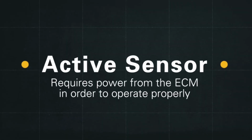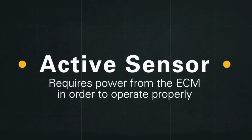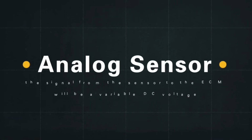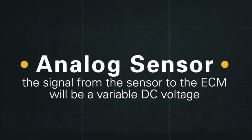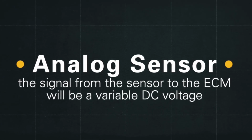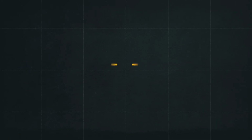We said we're going to be troubleshooting a -3 FMI code on an active analog sensor. Before we get too deep into the troubleshooting, I want to make sure we understand what we mean when we say active analog sensor. An active sensor requires power from the ECM in order to operate properly. In this case, we're dealing with a 5-volt sensor. Analog sensor, what does analog mean? Analog means that the signal from the sensor to the ECM is going to be a variable DC voltage that is going to change based on the parameter being measured by the sensor.